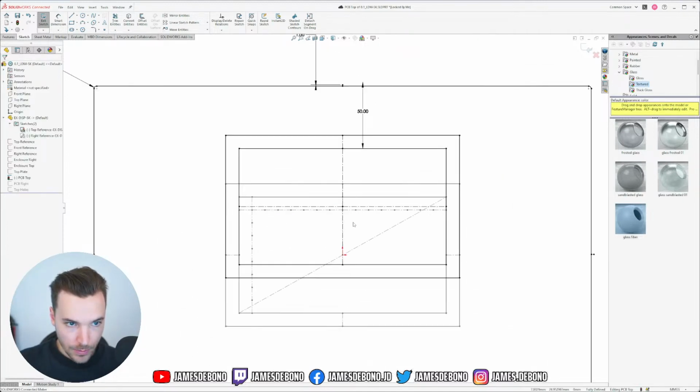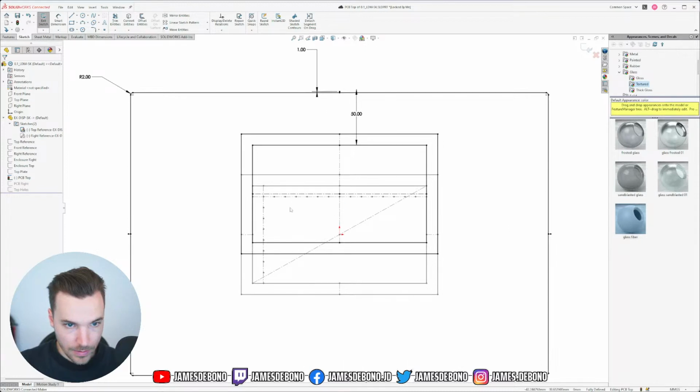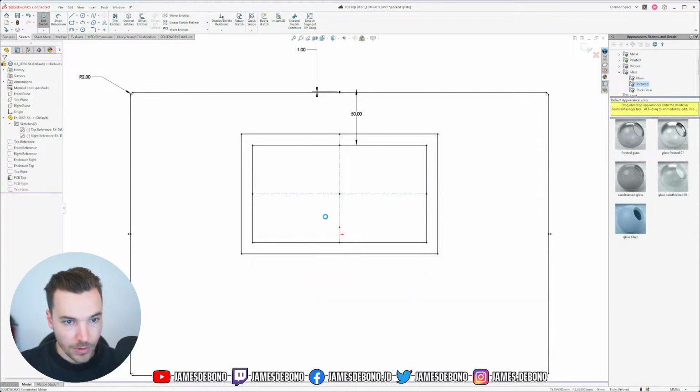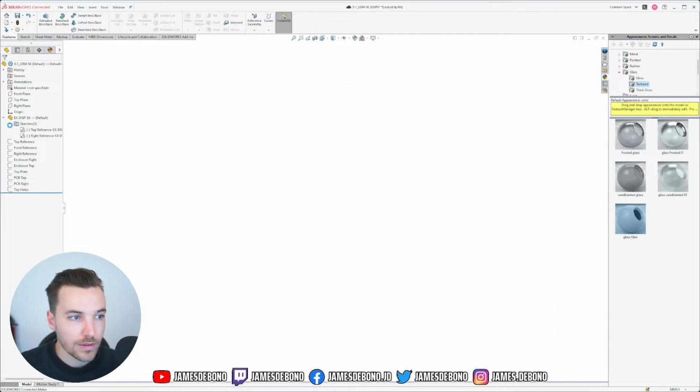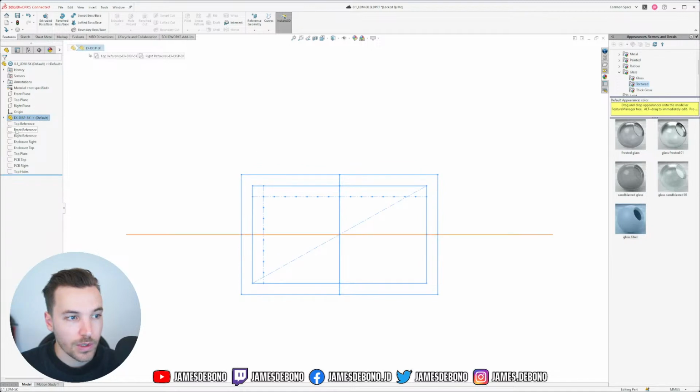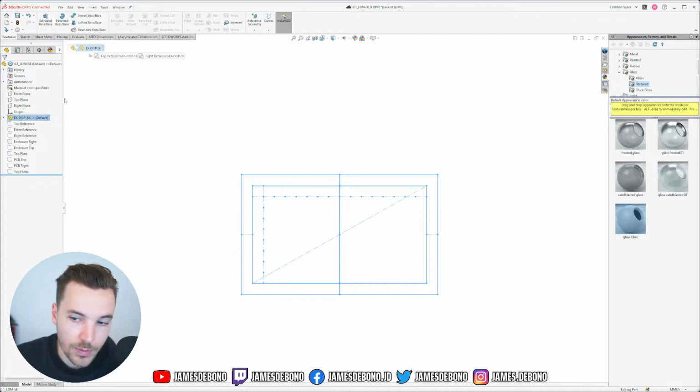Okay, so now my display, my movable display element on the PCB layout is referencing the sketches that I brought in from this other skeleton model. So if I go back and change that skeleton model for that particular part, it'll get updated here. And this means that I can use this skeleton model in other projects as well. So it's part of my component library now.